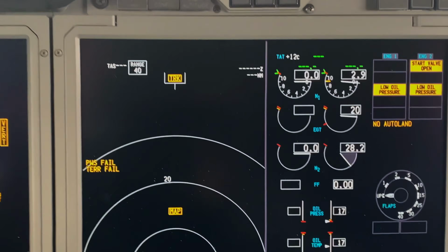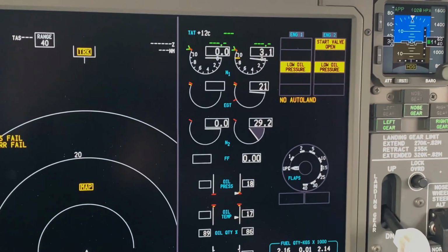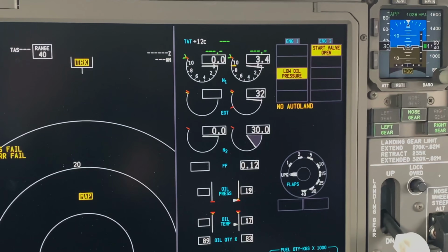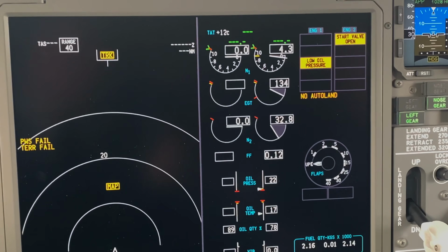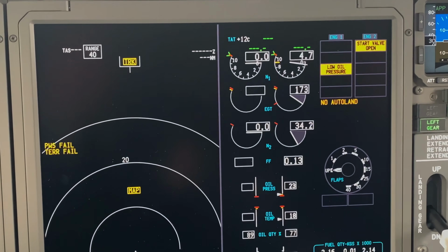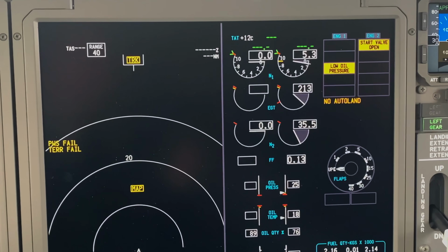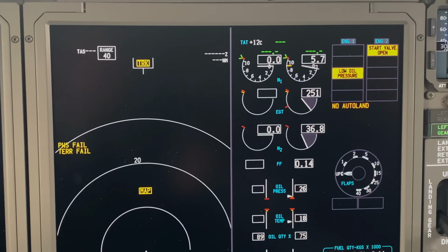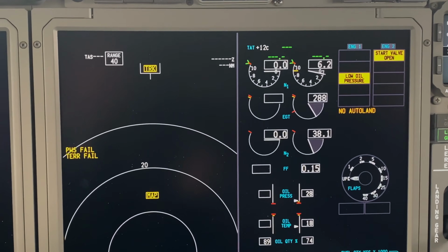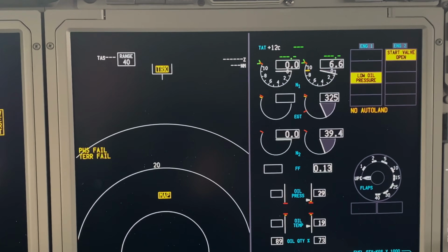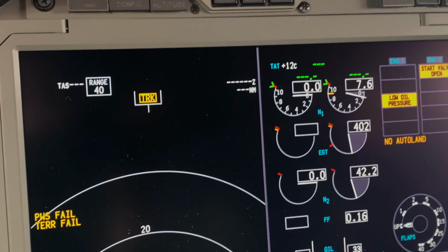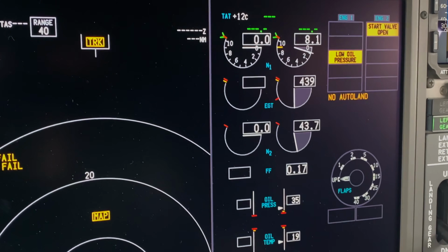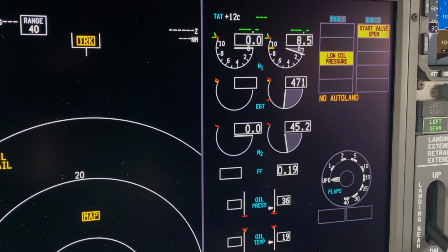Something new on this is the motoring flag, displayed when the engine requires a bowed rotor motoring sequence to cool it down. Max motoring should be no less than 20% N2. So we have to now monitor EGT and N2. Normally the engine should start in 15 seconds after the start lever switch is moved to the idle position.